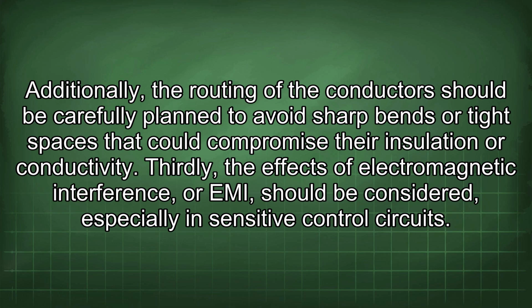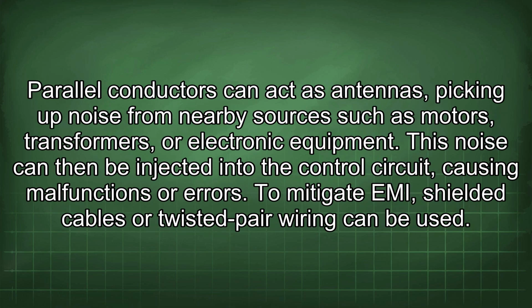Thirdly, the effects of electromagnetic interference, or EMI, should be considered, especially in sensitive control circuits. Parallel conductors can act as antennas, picking up noise from nearby sources such as motors, transformers, or electronic equipment. This noise can then be injected into the control circuit, causing malfunctions or errors.